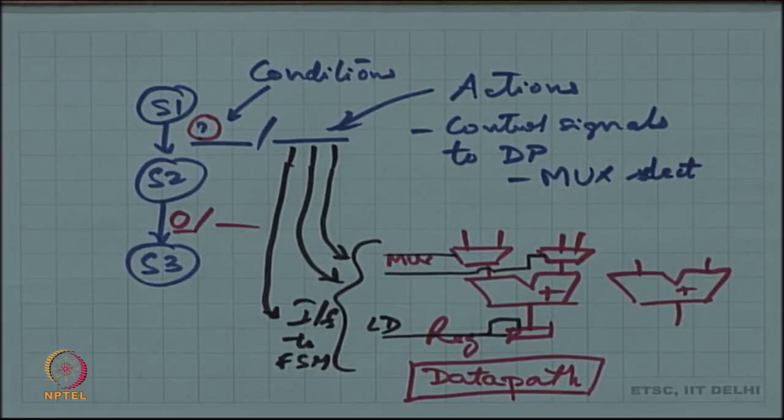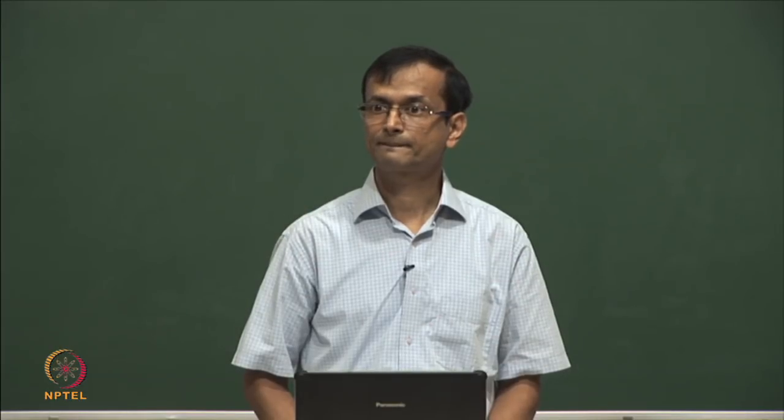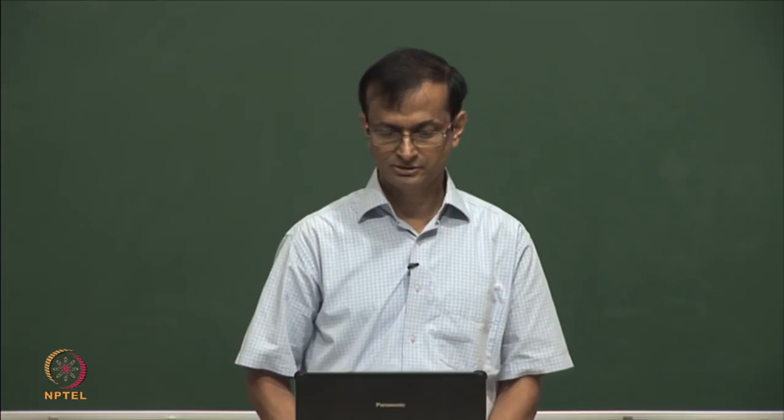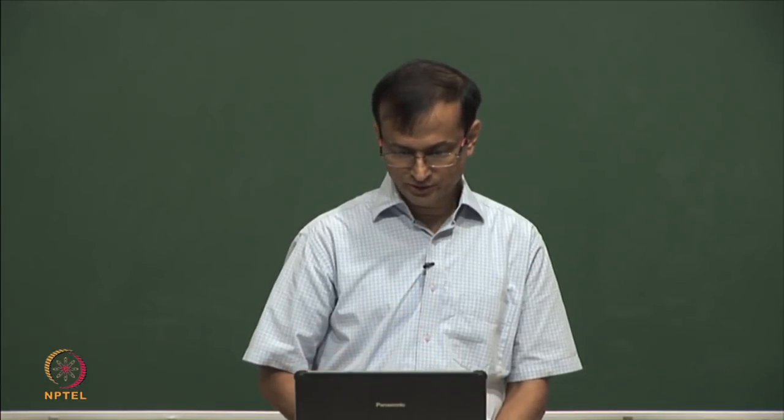You have to send that status information back from the data path into the FSM. But functionally, what does it tell us? If a carry exists, then? Depends on the algorithm we are proceeding with. The operation is like if carry exists, go to S2 state. But is that what the meaning is here? We go from S1 to S2.